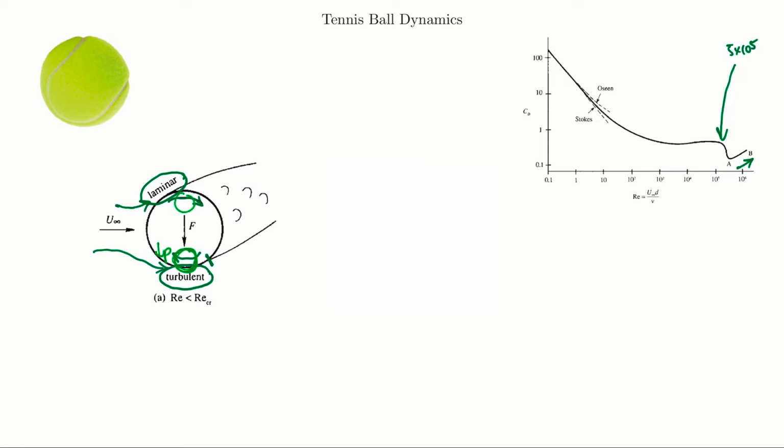But then on the top here, we had this separation point occur right here. So on the top, we have a higher pressure. So we would get a downward force in this case going this way, which is our negative Magnus effect. So that's the opposite of what I just drew above for the cylinder that we've seen at these low Reynolds number speeds, which again, rarely happens in practice.